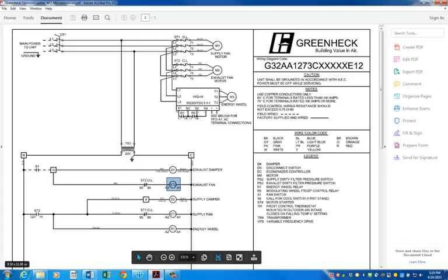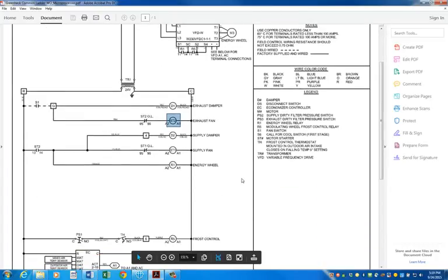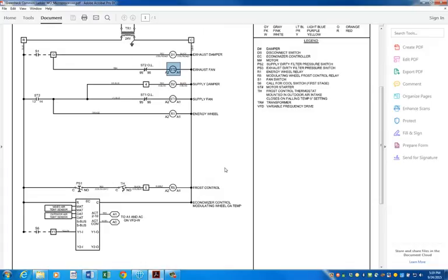Okay, so ST2 actuates the supply damper, energizes ST1, which closes these contacts on top here. Okay, you can see we have overload contacts with the manufacturer's terminal specs on it. So when ST1 is energized, these contacts here close, energize motor 1. So you can see there's a lot of similarities between these prints and what we studied earlier.